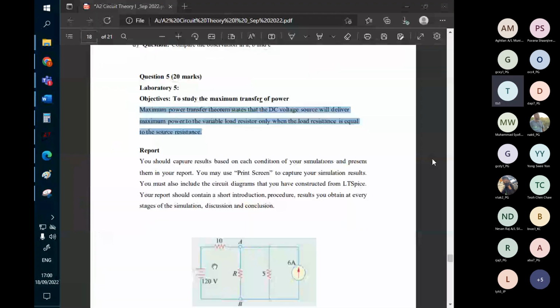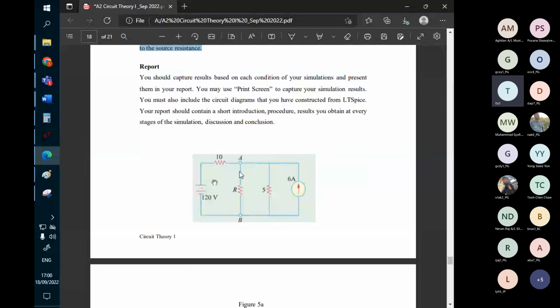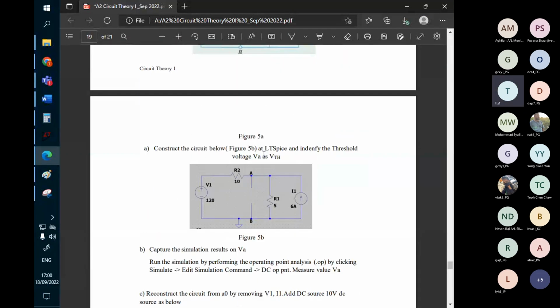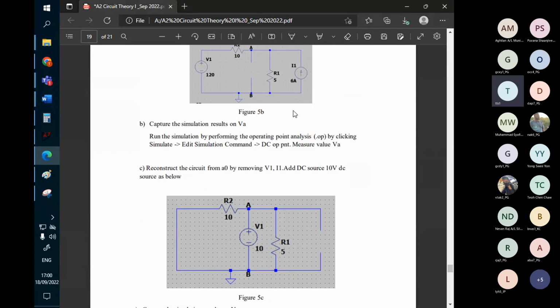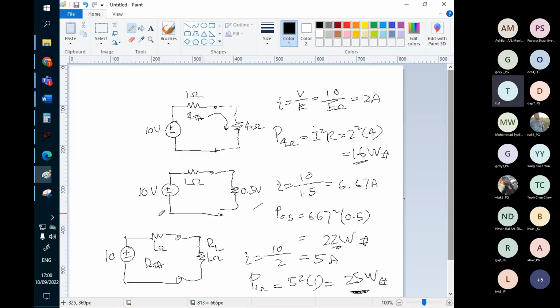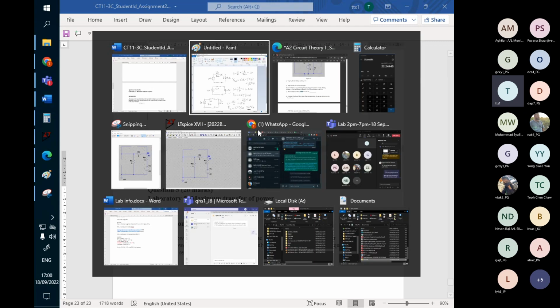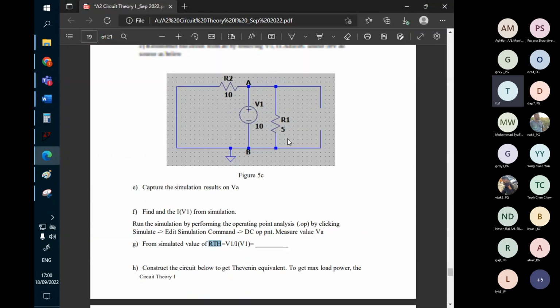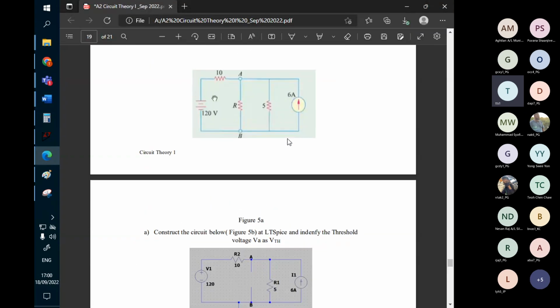Then when you come to the last experiment, we have the circuit like this. Of course, the first step is to reduce to something like RTH, with only one resistor and one power source, so that we can apply different loads. Okay. So which one is our load exactly?